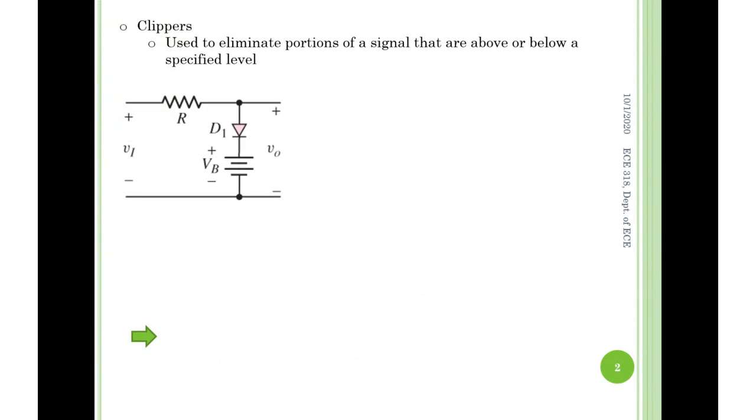Okay. If we just take a look at the circuit, it is not very difficult. It's not a complicated circuit at all, right? What you're seeing is one source, and the source is sinusoidal AC. Please remember this. In a Clipper circuit the input is sinusoidal AC. Sinusoidal large AC, not small signal AC. You probably want to take notes. Clipper circuit means large AC as the source.